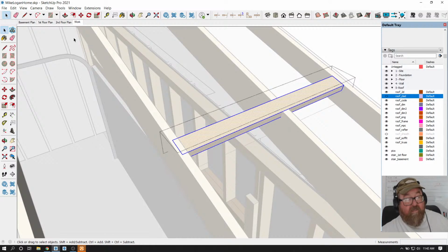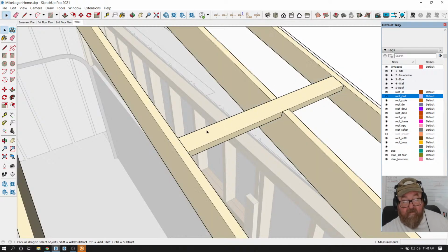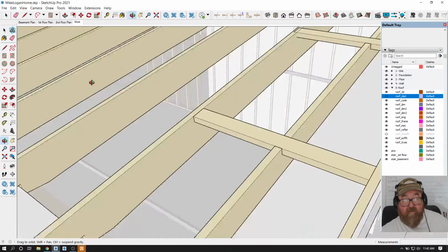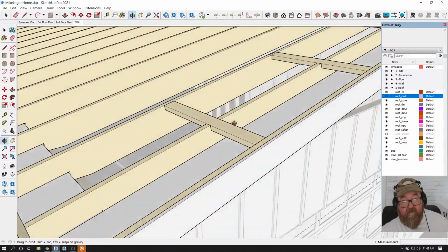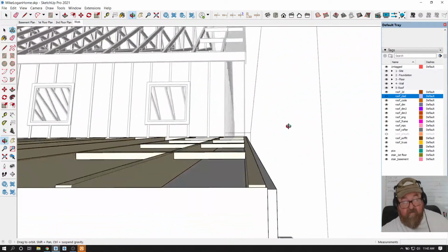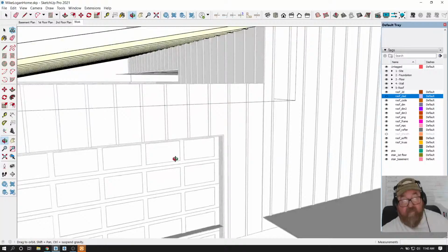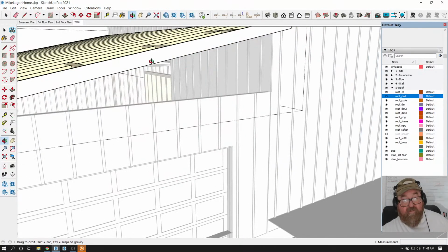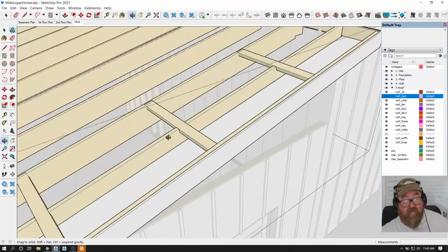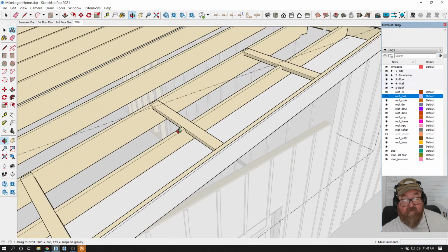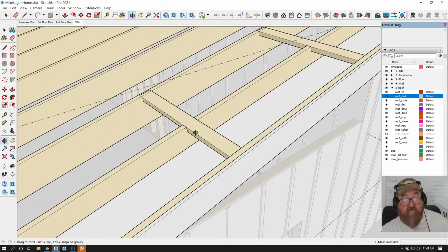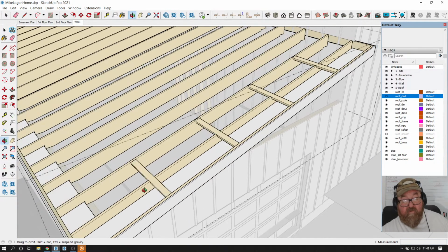Again, this is one of those things. It just goes to here. And what happens is your decking, after you nail your decking on top of this, it doesn't allow this to sag. Right? That's what its function is. And the studs that are on this end holding up that house line rafter gives you the ability to notch it out, because it's not a rafter anymore at that point.